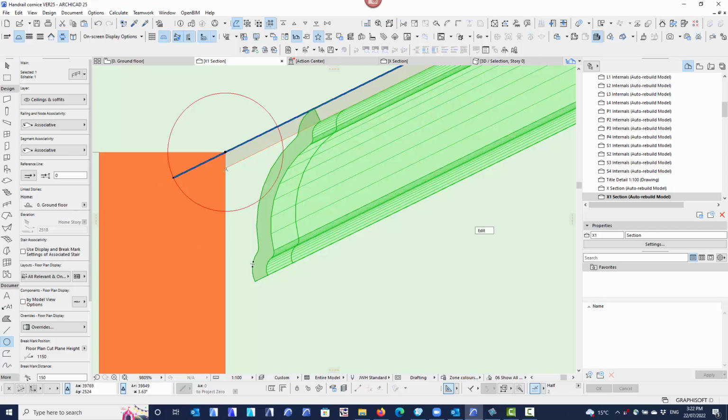Now that's moved one node, that's one end of the cornice. You can see one end of the cornice is gone. So even though I'm cutting halfway through the length of this cornice or this ceiling, it's dragged the end node. It knows where the end node is. And I just need to do exactly the same to the other node, and I just need to drag that down. And you can see now exactly what it's done is it's moved relatively and dragged that.